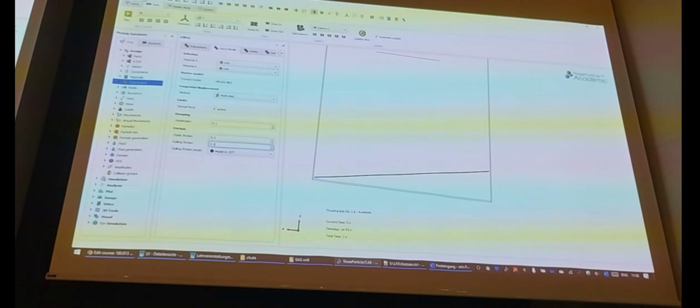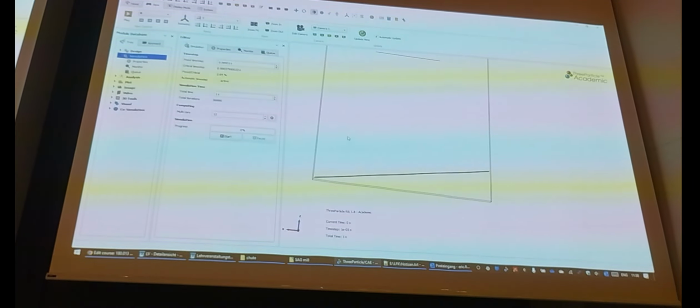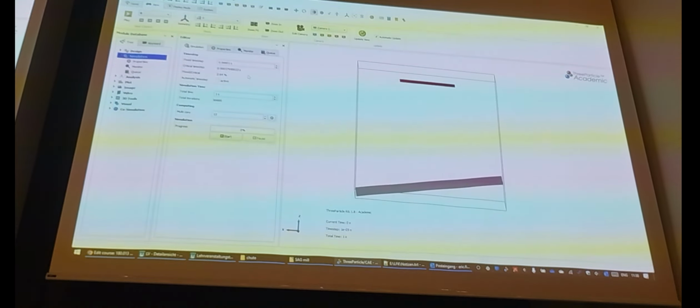Again, save, and I start the simulation. And before I start now, it's really slow. It's not really what I want. You can see here 2.64%. That doesn't say that much to you, but probably you remember also from the lecture, there was a time step that was critical, the Rayleigh time step. It was like this shock wave going through a solid particle. If you have a very rigid particle, a very small particle, you need a small time step. The program automatically computes in the background a time step that is suitable. And 20% of that time step is a good value to start with.